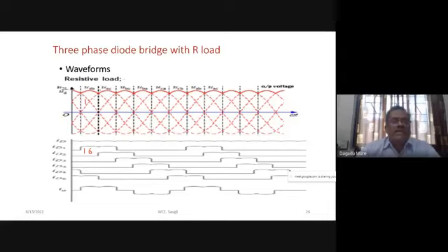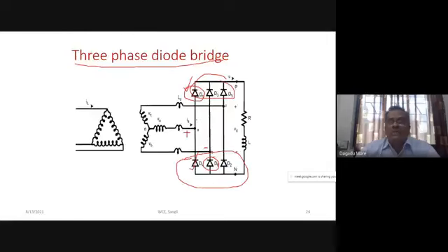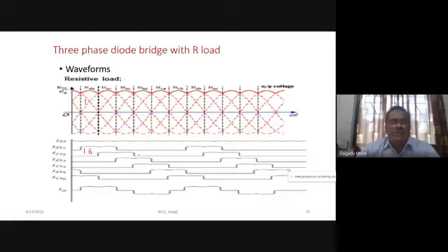Okay, if you have AC, what is the meaning of AC? In the next 60 degrees, AC means A is positive and C is negative. So A is positive, but now C becomes negative. When C becomes negative, we have seen which device will be forward biased. C is negative means our D2 will be forward biased and D1 will be forward biased, as A is positive. So in this period we have D1 and D2. So this will be the case. We have shown it here.